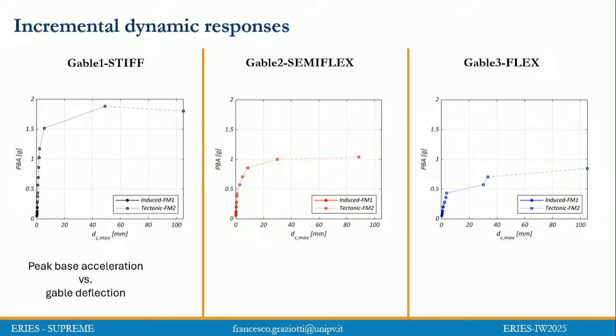You may see that, as expected, going from a stiff configuration, with the same acceleration top and bottom, towards a flexible one, with a higher acceleration at the top and also a very high differential displacement of the two tables, we had a pretty dramatic decrease in the acceleration capacity at the floor. Consider that today a lot of engineers are using these as input parameters, so the floor acceleration.